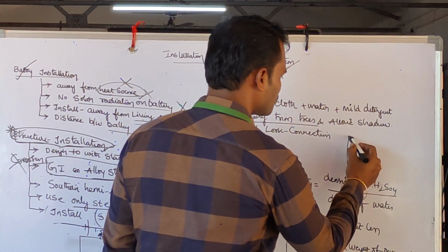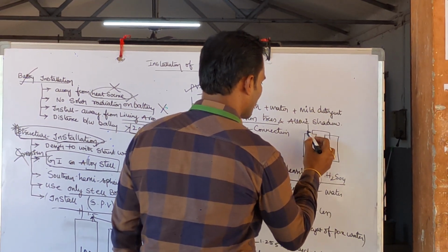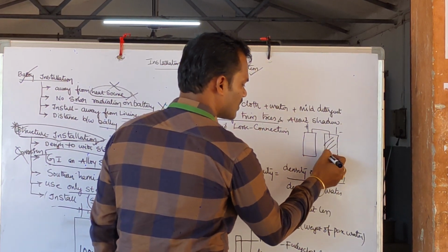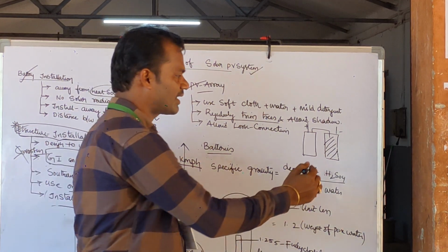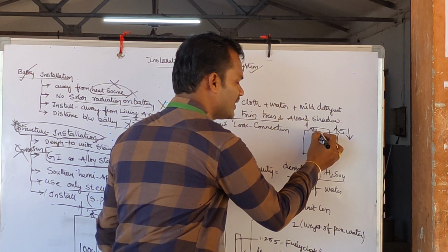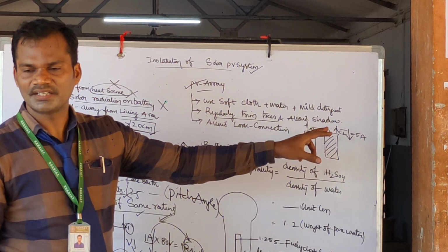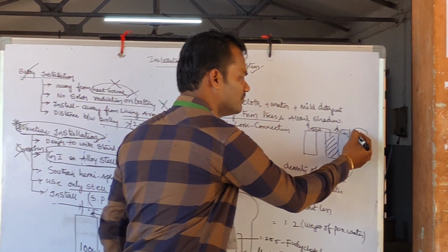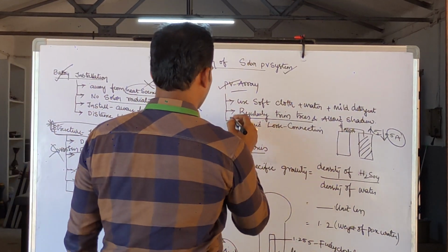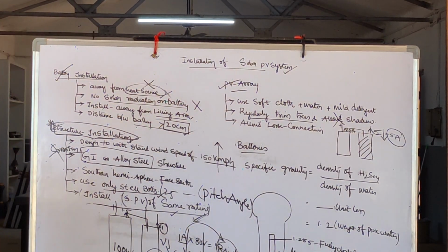So if you have two panels connected in series connection, so if one shadow falls on one solar panel, automatically the current magnitude will decrease. So this will generate some sort of 10 ampere current. The panel which is subjected to shadow will generate only 5 amperes. The resultant current of the total array only will be how much? 5 amperes. This is the effect of a shadow. Already we have discussed it.